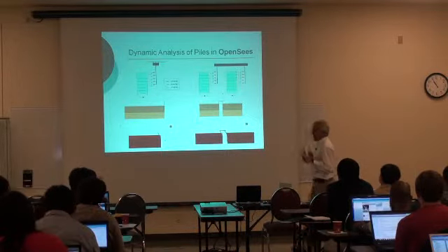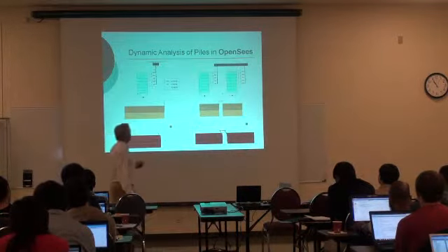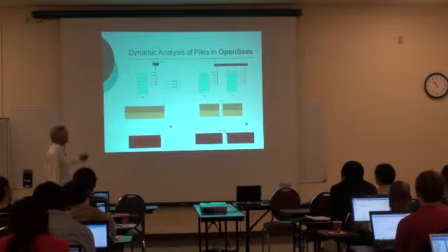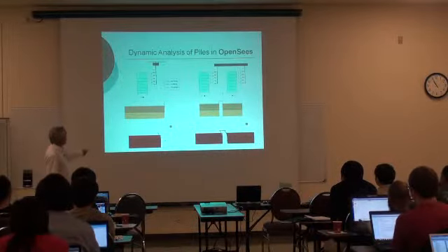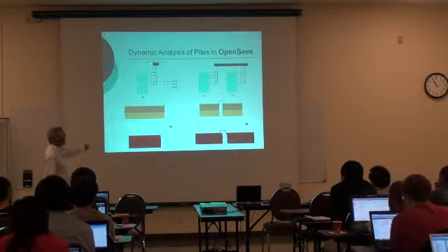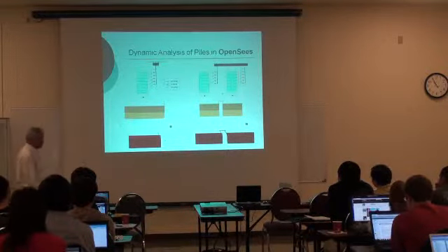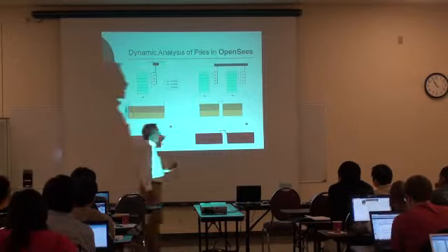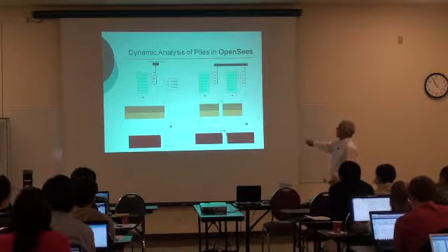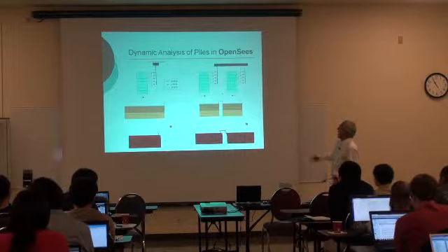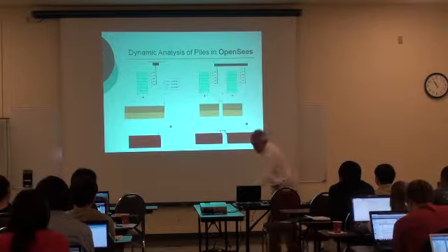So now, what we did is to develop very simple models. What I was interested in was trying to see, can we use a model that is as simple as this? Nothing. A soil column with springs, and this represents the bridge band. Or this bridge band with these two columns. Is this enough to capture some of the response? And the response I was interested in was the acceleration in the bridge band at the top, and maybe I was interested in bending moments along the pile.